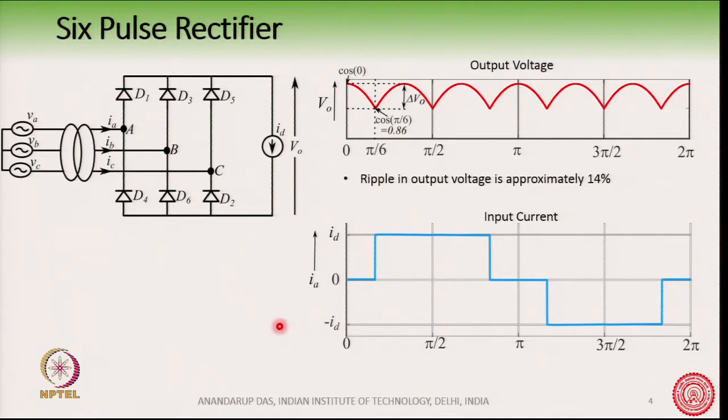Number two is that in case of a fault on the DC side, for example, if there is a dead short circuit fault here on the DC side, then the leakage inductance of the transformer helps us limit the rate of rise of the short circuit current. So, the transformer leakage impedance should be a certain value.